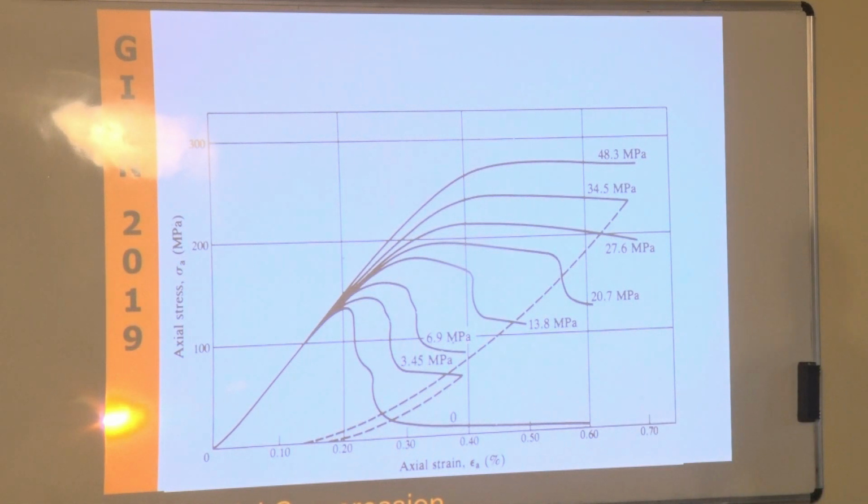So at the end, the cohesion is really helping you keep the sample together, even post-peak, after the rock is broken. So actually, cohesion is helping you avoid a collapse. That's a problem when you have an opening, because at the opening surface you don't have any support or confinement, and that is where most of the spalling happens and the rock can fall. But as soon as you go inside the rock, you still have some confinement that helps reduce the damage and how it propagates.